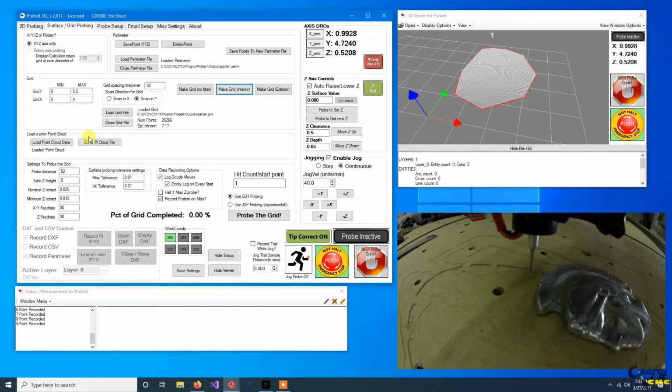And just to give a quick demonstration of how you set this up then, probe distance, again, we're sitting at roughly 0.52. We want it to go all the way down to the bottom. So we'll keep this at 0.52. Our safe Z height will be 0.5. A nominal retract to 25 thou. A minimum retract to 15.